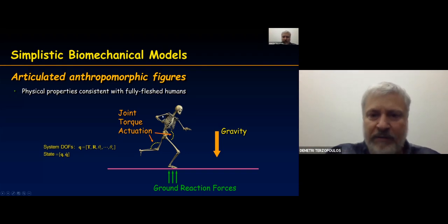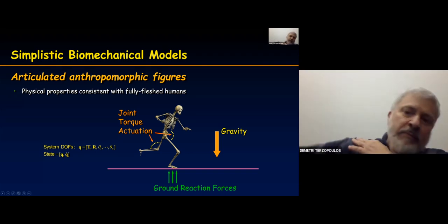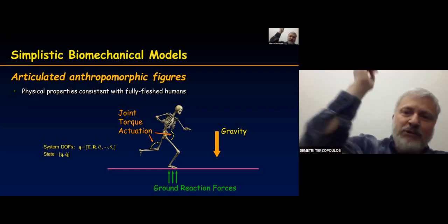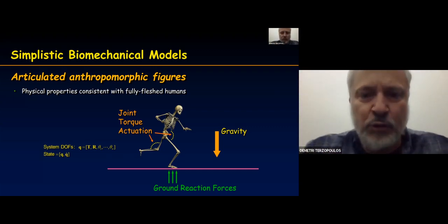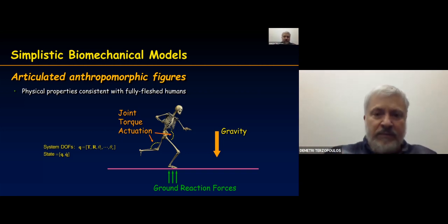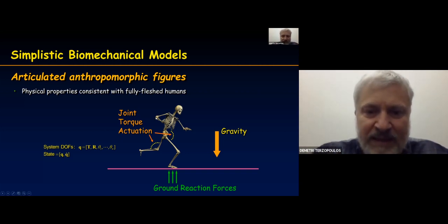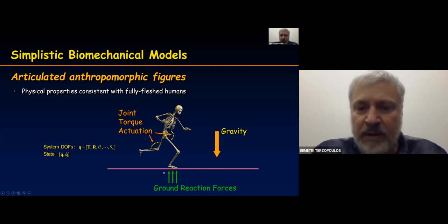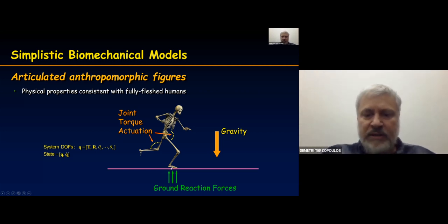And in the body, we have three degree of freedom rotations, say in the shoulder, essentially 2 degree of freedom rotations on elbows, and so on. Each of the joints have different numbers of rotational degrees of freedom. And so we can put these virtual motors in there and then simulate this structure in gravity with ground reaction forces. So there's physics over here in this articulated structure, and it's contact with the environment in which it's situated.